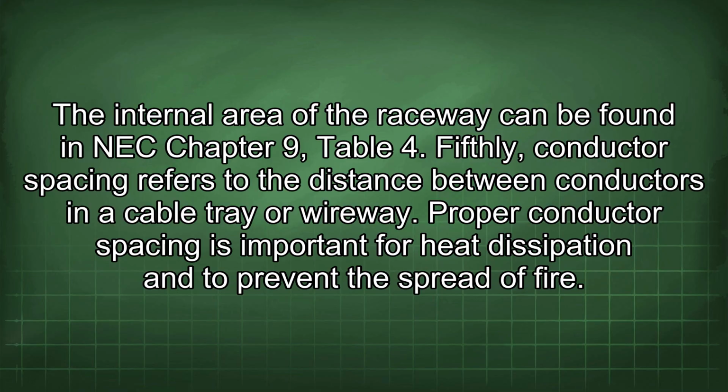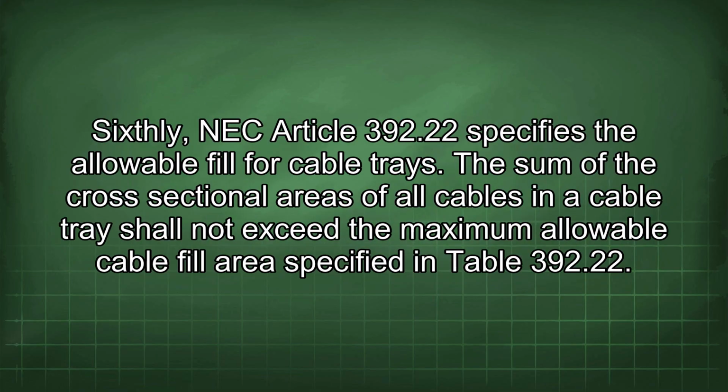Fifthly, conductor spacing refers to the distance between conductors in a cable tray or wireway. Proper conductor spacing is important for heat dissipation and to prevent the spread of fire. Sixthly, NEC Article 392.22 specifies the allowable fill for cable trays.